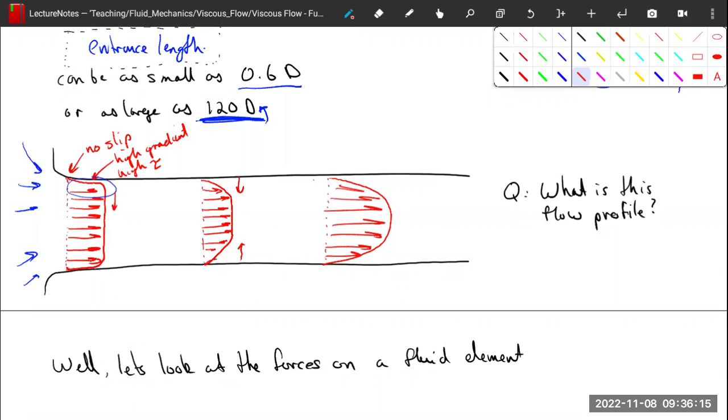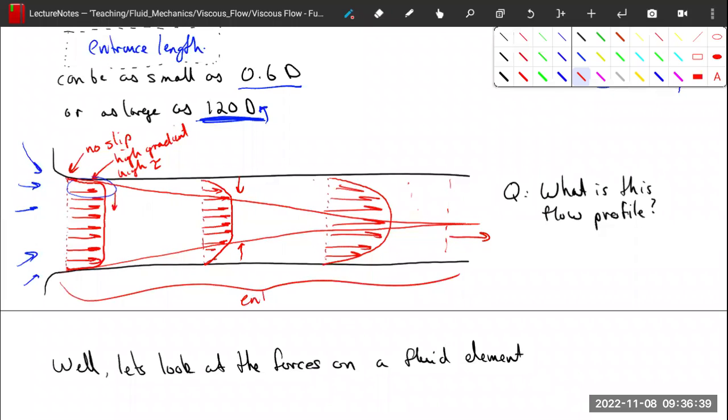And we'll talk about this more. These are called boundary layers. The boundary layers grow, which is the influence of the wall, like this, until they intersect. And where they intersect is where the viscous effects of slowing down the fluid have fully spread throughout the pipe, and our flow profile will be the same no matter what moving forward. And this is the entrance region here. Entrance region.